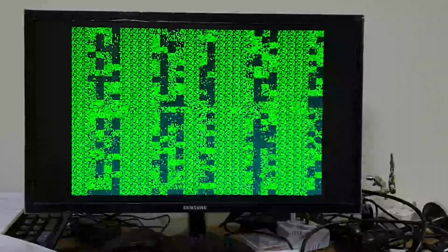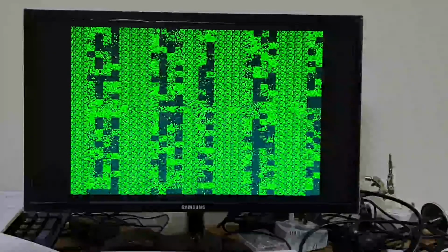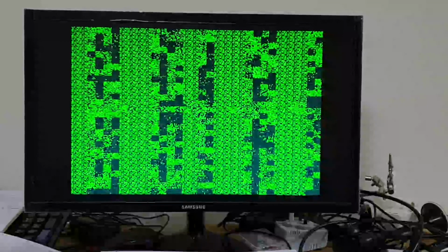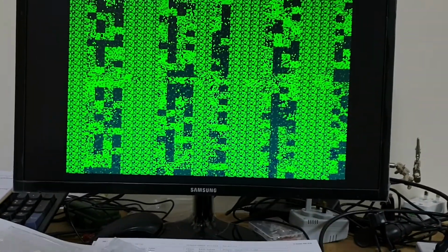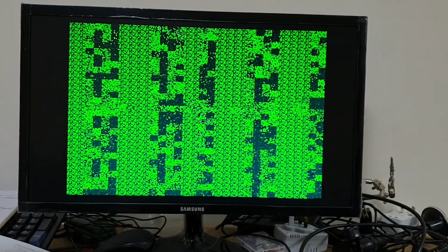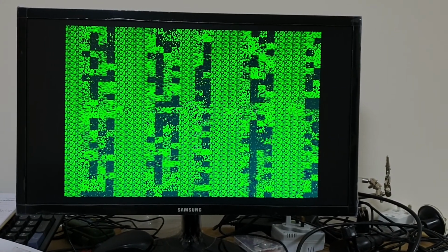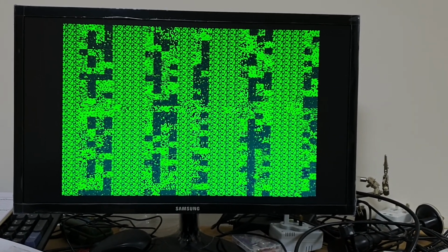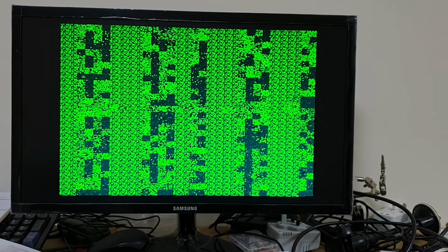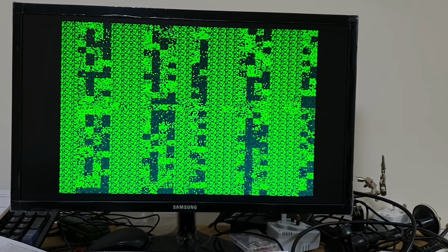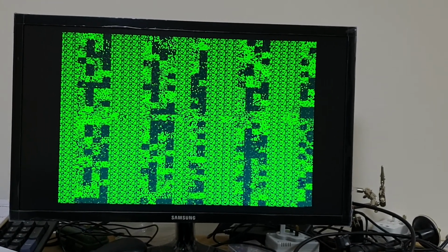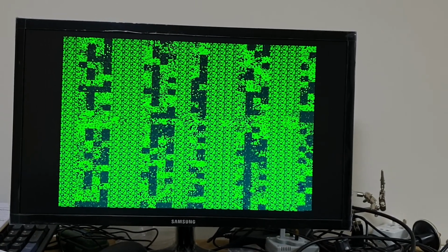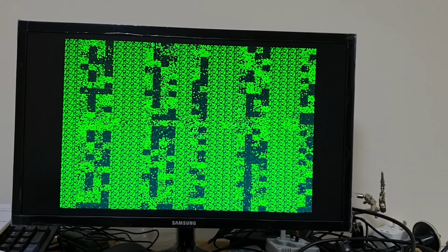and depending on the palette entries, because I think if I remember rightly, the bottom 4 bits of the character color RAM, which starts at 9400 in hex, contain the palette entry, and then the next 2 bits contain the upper high bits of the character index, and then the next 2 bits are horizontal and vertical character cell flips.